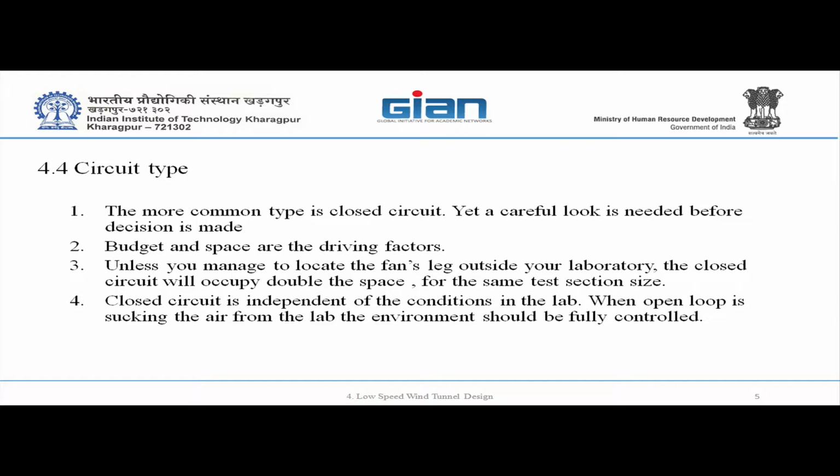If you are sure you can control the environment, you can go for the open loop because it's less cost, and it could even be easier to control the turbulence level there. In the closed circuit you have turning vanes and other elements adding noise to your flow, so you have to work again on decreasing all the disturbances.